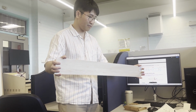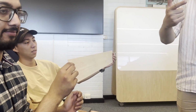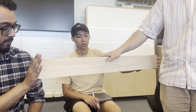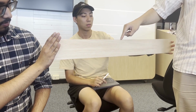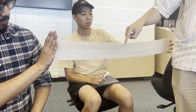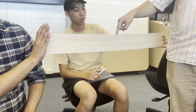So what I'm going to do is, could someone hold this? Or maybe you hold one end, you can hold the other end, okay? Sorry, hold it more towards that way. So if I apply a point load in the middle, right? This is quite a slender member, right? What do you think happens? It's going to start to fall out like that. Isn't that a bit weird? Why is it doing that? Because it's more prone to buckling that way. That's partly the reason. Okay.